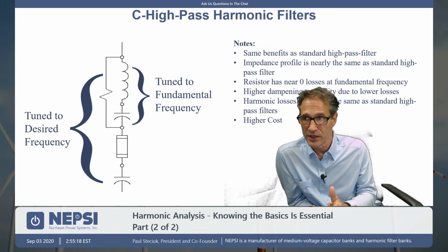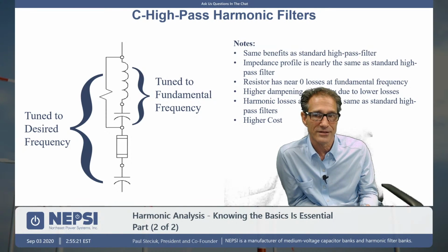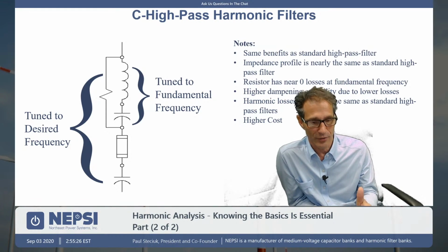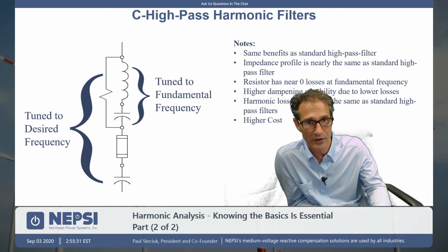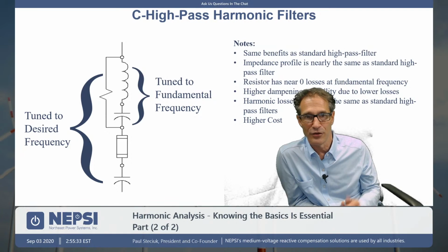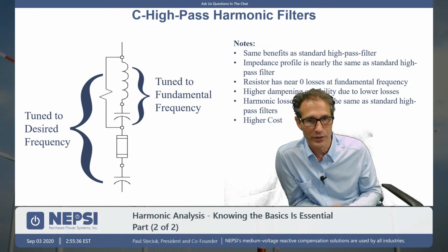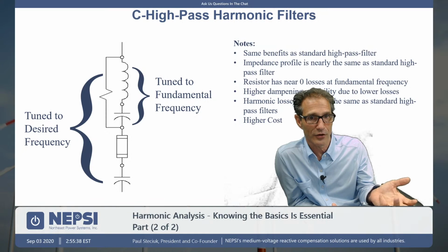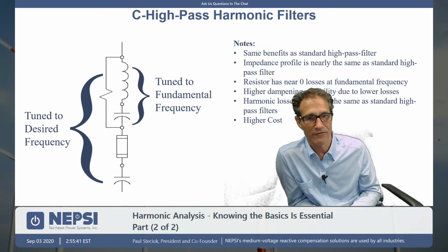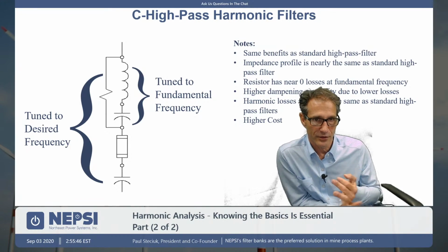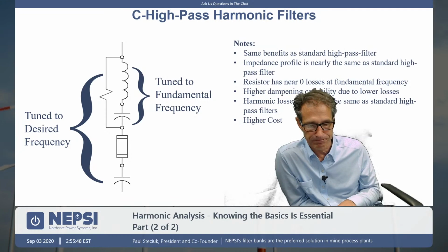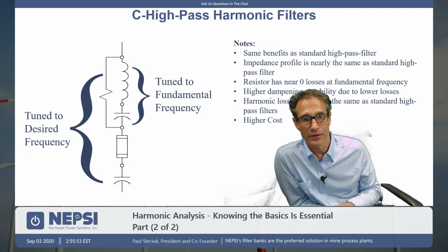But your statement is the majority of harmonic currents on the system, the third harmonic currents, are zero sequence. The harmonic filters, medium voltage, 2.4 kV through 38 kV, are ungrounded. So therefore, you'll typically have an interaction between the zero sequence harmonic currents of the third and the harmonic filter. They're non-existent, not an issue. But there are applications, and arc furnaces being one, and cycle converters being the other.